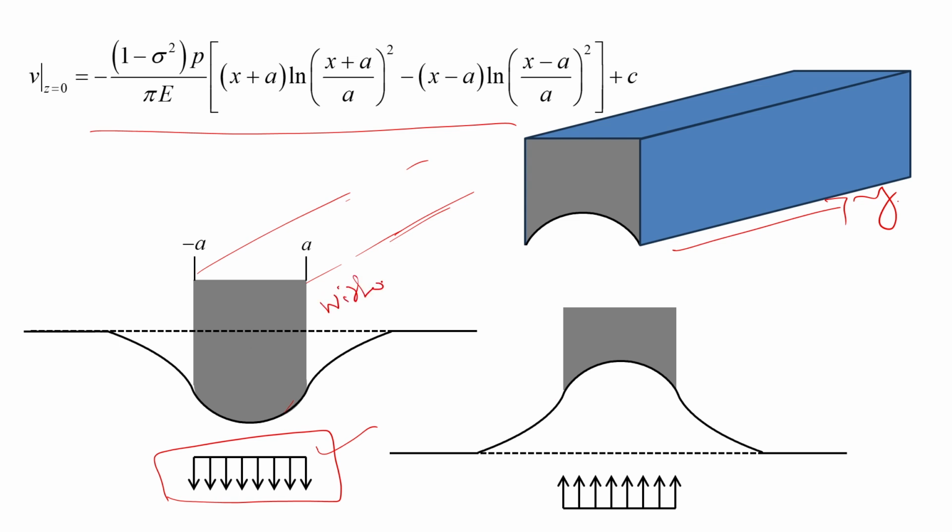This is without adhesion. But if we consider adhesion, then what kind of indenter will lead to this kind of normal distribution of the load? The indenter has to be of this particular form, because it is a rigid indenter, remember that. Suppose there is sufficient adhesion and we first bring it in contact and then try to pull it by applying some load; then the deformation will be something like this.